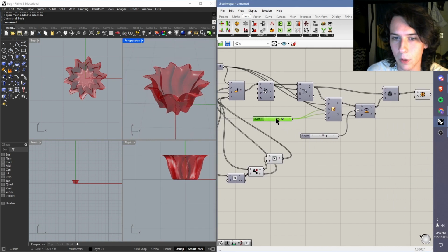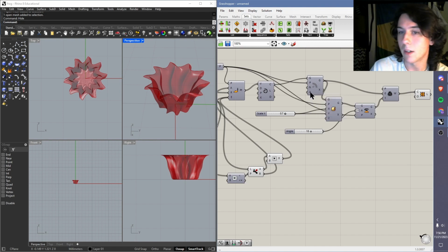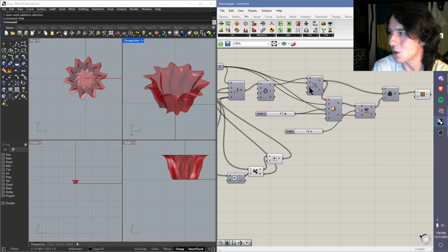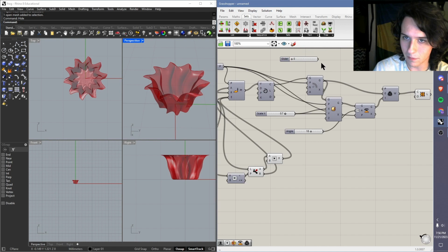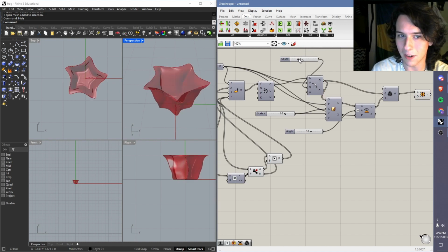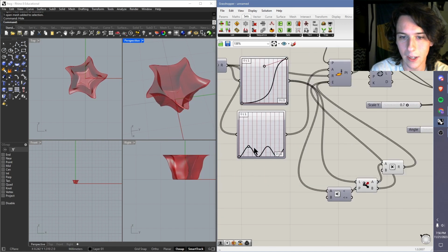So let's talk a little bit more about what you can customize about these. Our polar array, we haven't even touched the number of elements. I don't recommend changing the angle. We definitely want a full circle. However, if we change the number of elements, let's create a slider from 0 to 20 maybe. It gets mad at us with 0, kind of obviously maybe. If we set it to 5, it's a much simpler looking lampshade, and we can change this angle to create some crazy curves on it. And we can play with these until this looks like what we want.